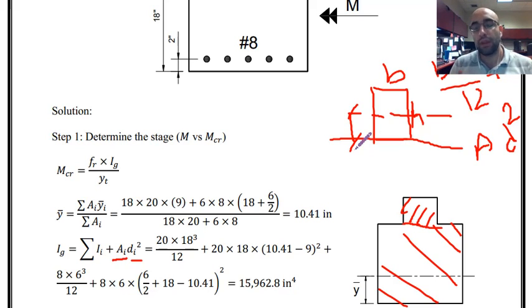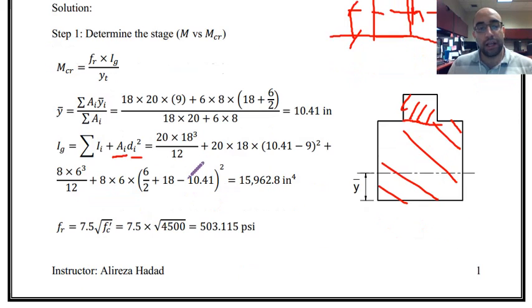That is the major rule, or the basic rule, that we have when we are calculating the moment of inertia about different lines or different regions other than the centroid of the shape. So area multiplied by the distance from the centroid of the shape to the place where we are calculating the moment of inertia about. So with this knowledge, I can calculate the total moment of inertia of this section.